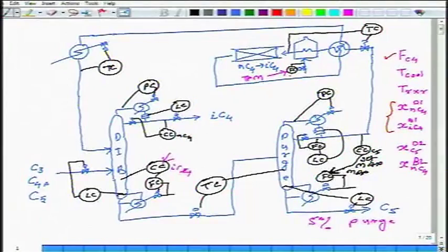That is why, because furnace duty becomes a constraint that will be active at maximum production, I am not using it to control anything, so that this throughput manipulator can be taken to 100% and left there. That means the furnace duty valve is fully open. But I need to control the temperature of the reactor. How do I do it? By adjusting the flow to the reactor. That's what is being done by this temperature controller. Yes or no? This is the reason why it was done.